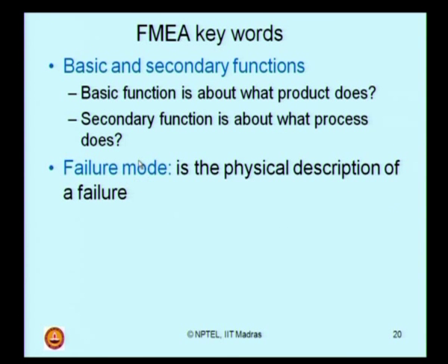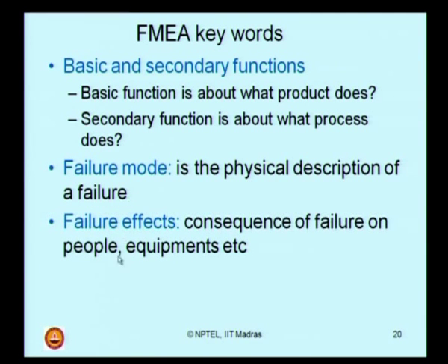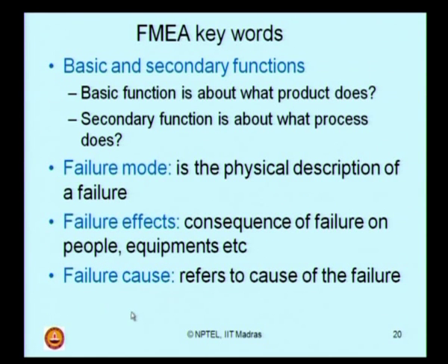What is a failure mode? Failure mode is the physical description of a failure. You have got to physically describe how a component will fail to perform its intended function. Then what is a failure effect? Failure effect is nothing but the consequence of that failure on human safety, maybe on people, maybe on equipment, etc. Then what do you understand by a failure cause? This refers to the reason this failure had occurred, the cause of the failure.